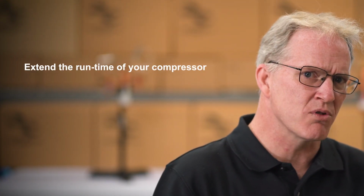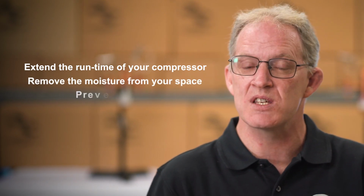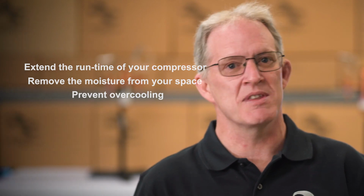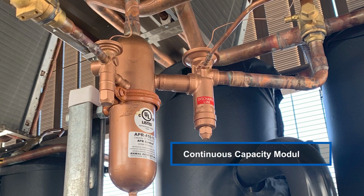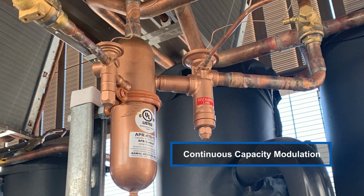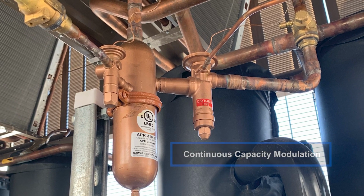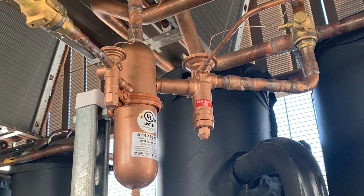Having an APR control in your system will extend the runtime of your compressor to remove the moisture from the space while preventing overcooling. Compressor runtime is the name of the game when we're talking about moisture removal and preventing high humidity. The APR control is designed to provide continuous capacity modulation to keep the compressor on and in a dehumidification mode, all while preventing overcooling of the space.